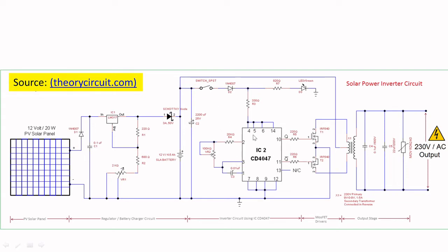Basically this CD4047 can be used as a multivibrator. Do you know what is meant by a multivibrator? A multivibrator is a switching circuit. It generates a non-sinusoidal wave, like a square wave, rectangular and sawtooth waveform. So people usually say it is a frequency generator circuit.